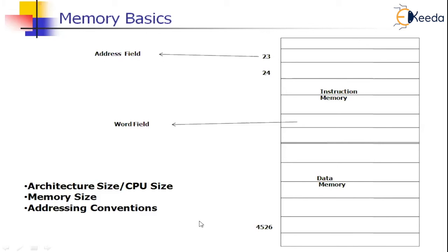As the main memory is 4096 words, the address part must be 12 digits. By using 12 digits, any location in the main memory can be identified by a 12-bit address. Anywhere between 12 zeros and 12 ones, you will be able to address a specific memory location. So the address part must be 12 digits in our architecture, and the data part should be 16 bits.